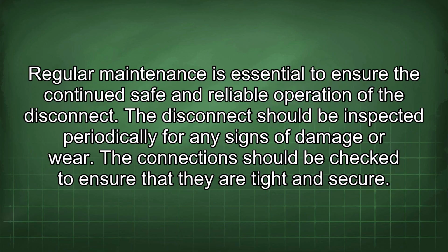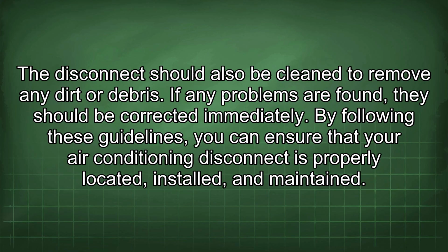Regular maintenance is essential to ensure the continued safe and reliable operation of the disconnect. The disconnect should be inspected periodically for any signs of damage or wear. The connections should be checked to ensure that they are tight and secure. The disconnect should also be cleaned to remove any dirt or debris. If any problems are found, they should be corrected immediately.